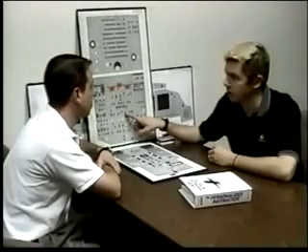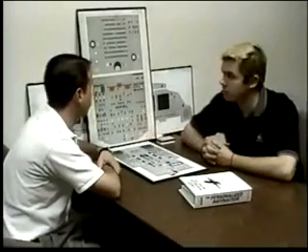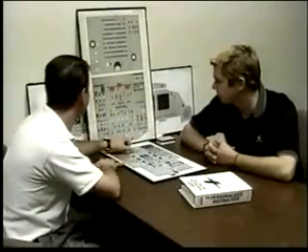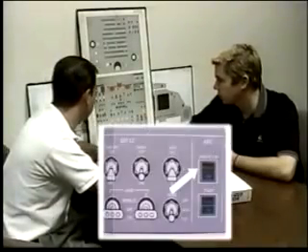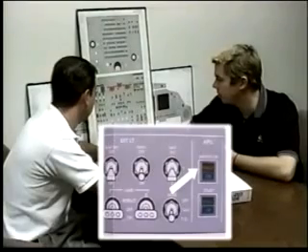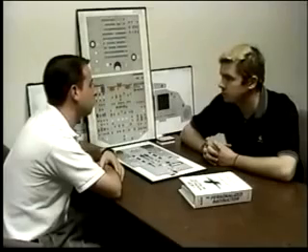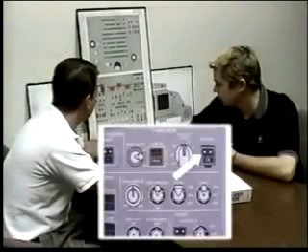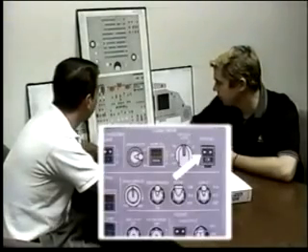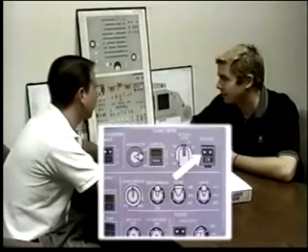So with an absence of the on light here, the APU must be powering the aircraft. What about fault in the APU master switch? That just indicates that an abnormal APU shutdown has taken place. Do you know what type of shutdown has occurred? No clue.